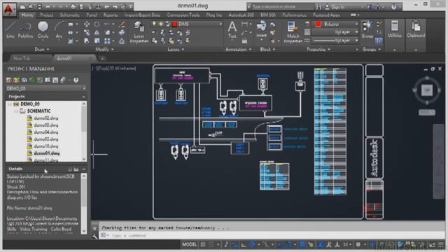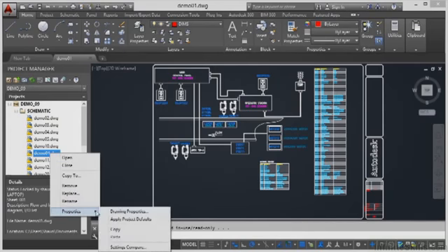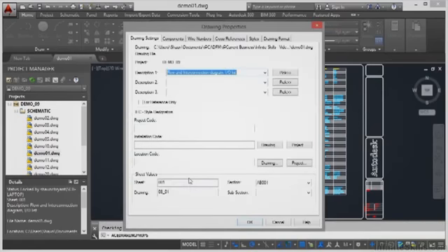However, something you can do with your drawings is change your drawing properties, change the numbers that appear here on the drawing. Now, what you can do here is you can specify a sheet number for each drawing. So Demo 01 is the current drawing. If I click there like that and select it, don't rename it, just click on it so it goes blue like so. Right click, Properties, and go to Drawing Properties. That'll bring up the dialog box.